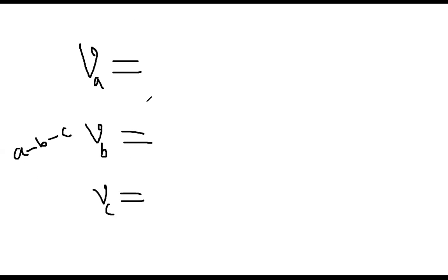Now we want to analyze this unbalanced system with the help of the symmetrical component tool, and I want to convert each of them into a three-phase balanced system. So now everybody see what I am doing. VA1 plus VA2 plus VA0. So this means I decompose this A phase into three components, VA1, VA2 plus VA0.